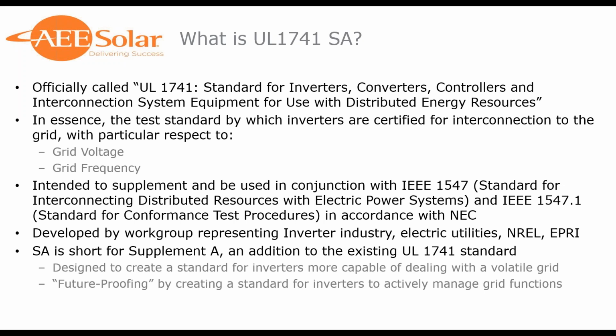Alrighty, what is UL 1741 SA? You're going to hear it referred to as SA, as Supplement A. So officially, the standard is UL 1741, standard for inverters, converters, controllers, and interconnection system equipment for use with distributed energy resources. I thought about creating a funny acronym to shorten that up, but it's really long and I couldn't find anything. So that's the official name. In essence, this is the test standard by which inverters are certified for interconnection to the grid with particular respect to grid voltage, grid frequency.